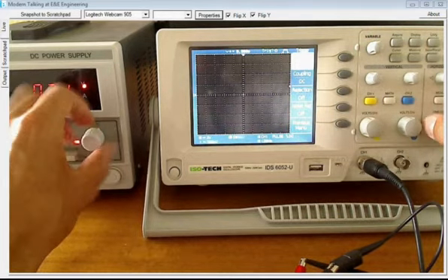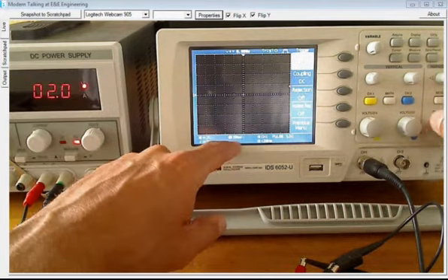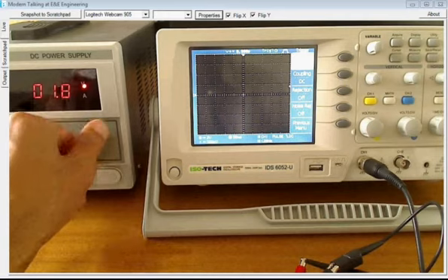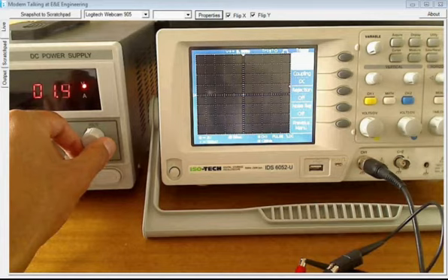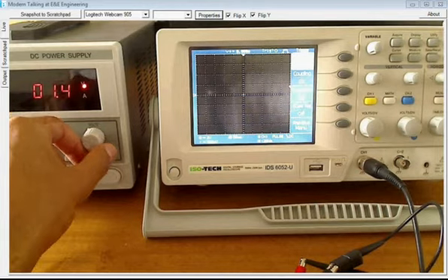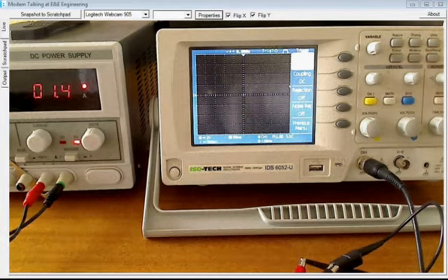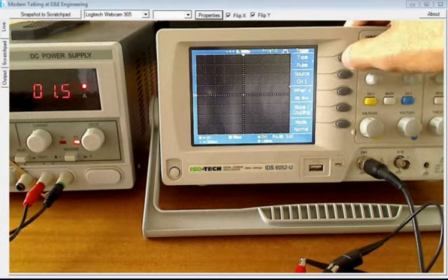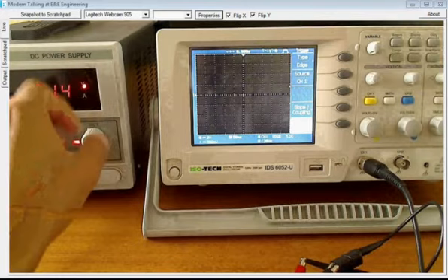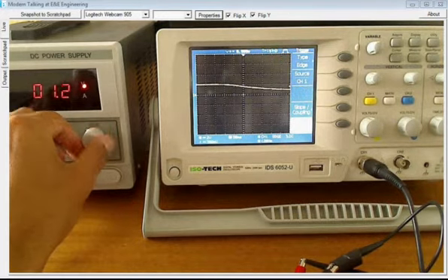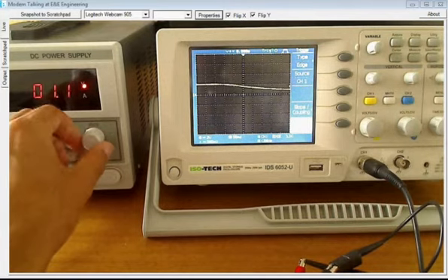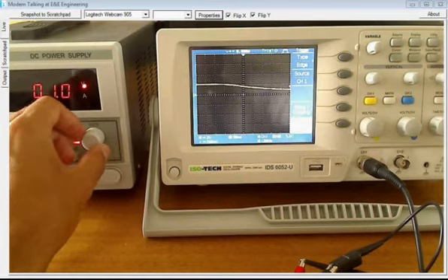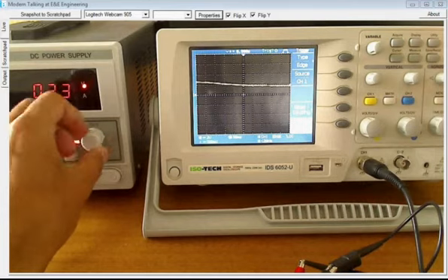So I'm at a high voltage, and I'm just going to zoom in a bit. So I'm changing my time. I'm changing it to 100 milliseconds, so it updates a bit faster. And if I drop the voltage level I'm supposed to trigger, I'm just waiting for it to detect it. Ah, should have waited for an edge. There we go, and it's triggering. So I'm triggering on a falling edge of a signal, and you can see every time I go through that level, which is at 1.78, it will trigger.